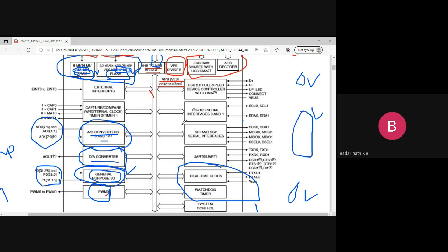You can connect an SD card, store your songs, provide a panel to select the song, and play them, connecting a speaker using an audio amplifier if required. Otherwise, you can use one transistor and connect to your speaker directly. So A out is the place where you can generate your analog signals, including sound.